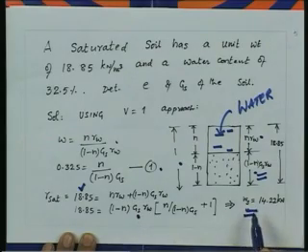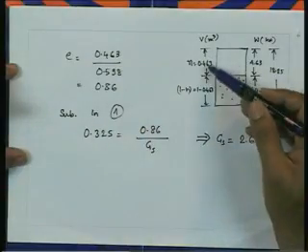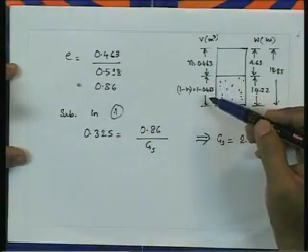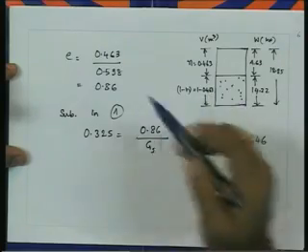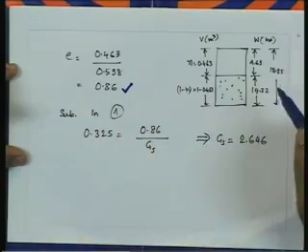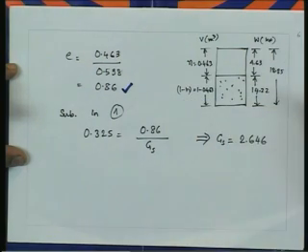So, from there, by using this unit volume approach, we get the porosity n as 0.463 and the volume of solids as 1 minus 0.463, so the void ratio is 0.86, that is e is equal to n by 1 minus n.